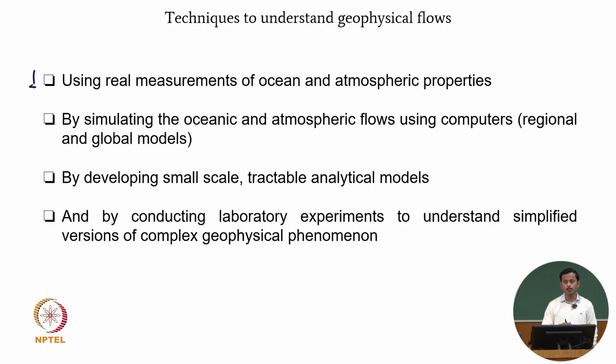This is done by putting a probe, for example, a temperature sensor, a salinity sensor, which is actually measured by a conductivity probe. So salinity is inferred from conductivity. And atmospheric properties, for example, you want to measure humidity or the temperature or the direction of wind, you put relevant sensors in the atmosphere.